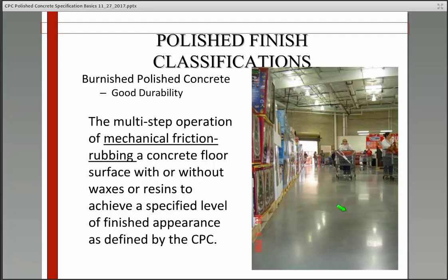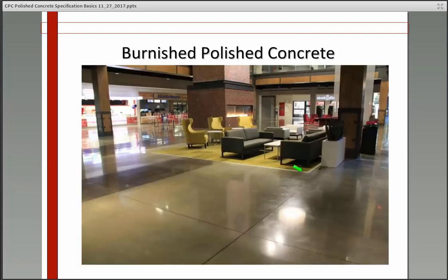And as you go from grit to grit, that will also allow the concrete to shine to whichever level you are interested in. As far as what the architect needs to know, this process will not expose aggregate. It will not expose fine aggregate. So the choice here is if they want a floor that can have some shine, not have a sealer on top, and be densified to rejection, so it's highly durable. That's why somebody would use this product. This is an example.